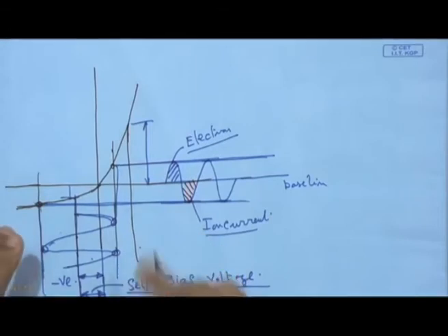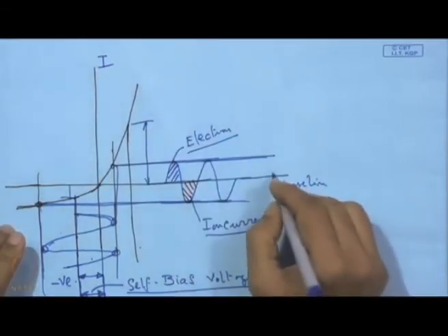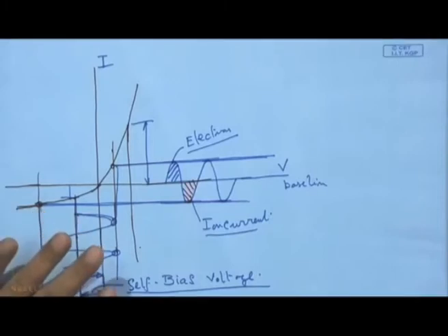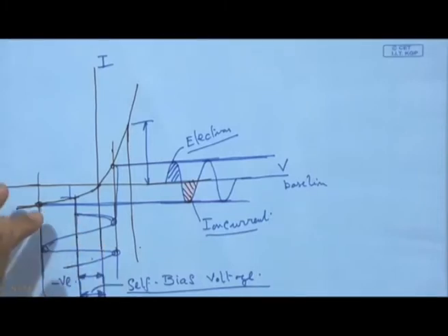So, from this illustration also we understand that a self bias is developed on the cathode surface of a non-conducting cathode or target surface, and this is possible because of this alternating supply, and at the same time this electrode is serving just like a capacitor in that circuit.